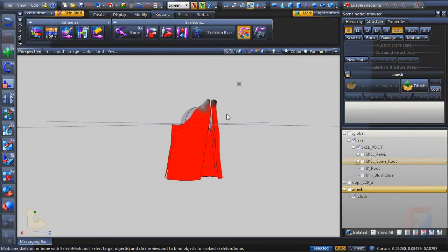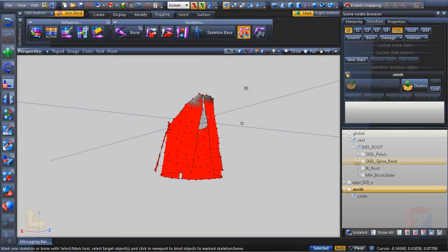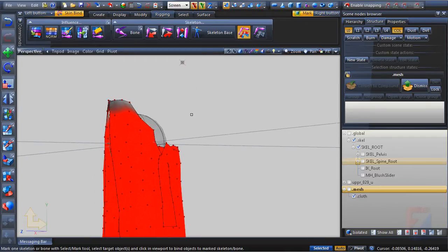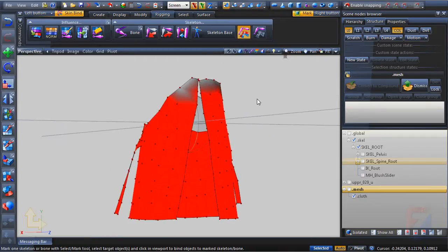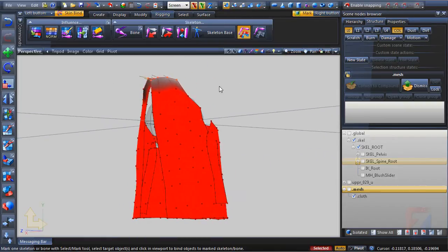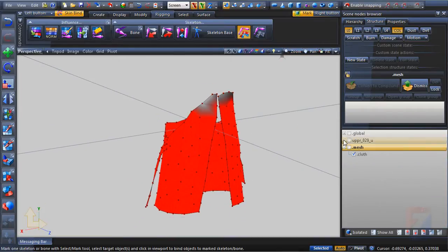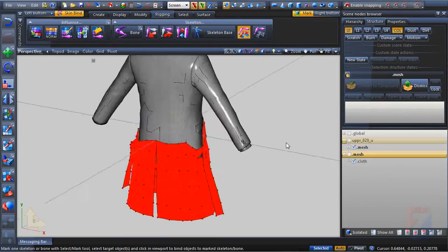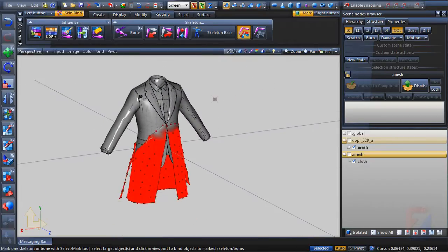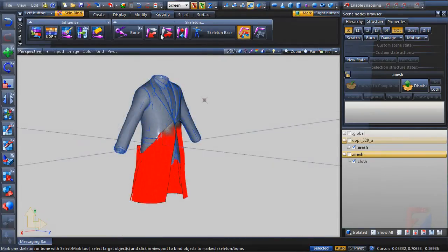It is essential to assign correct bones for the static points, the points that will be controlled by the skeleton. We do so by copying weights from the original mesh object, if possible. So we use rigging influence copy.